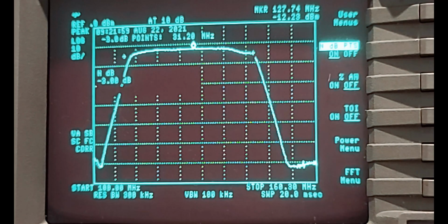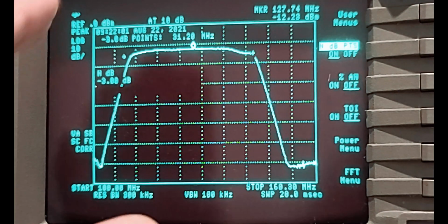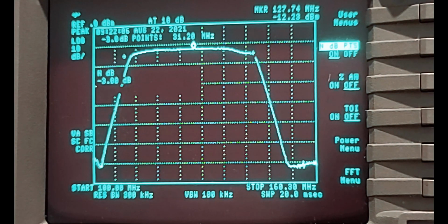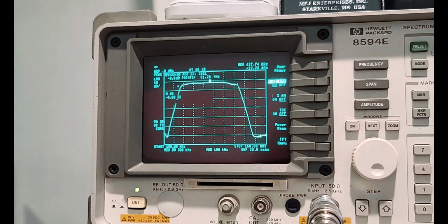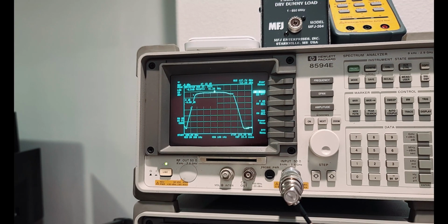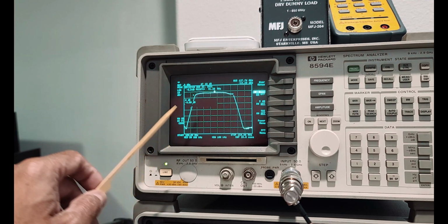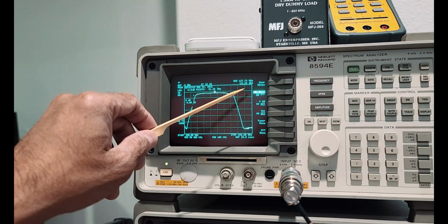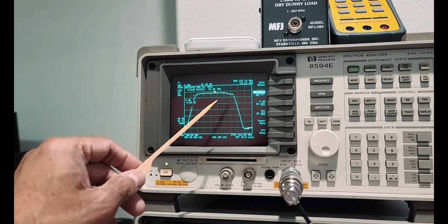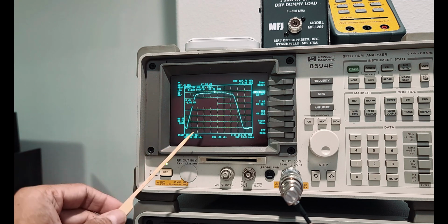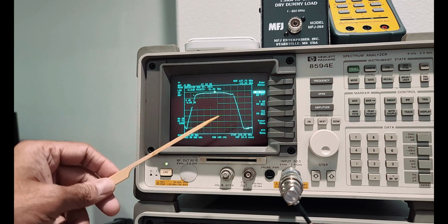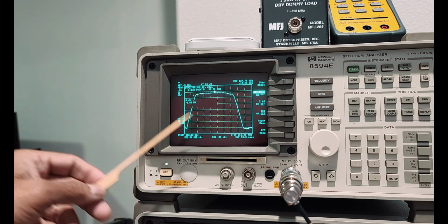All right, now imagine having to do that with a duplexer. If you were to do a similar tuning operation on a filter or a duplexer, the exercise we went through where we used the trace to hold the trace, let it plot a couple of iterations, and then determine if you need to adjust your tuning knobs of a filter, I mean, that's a lot of back and forth.